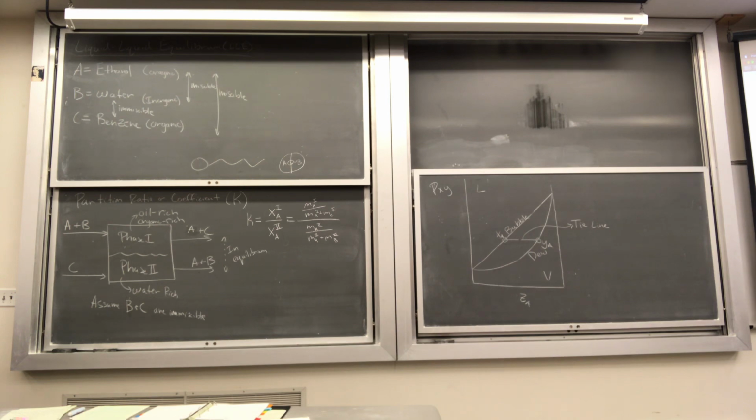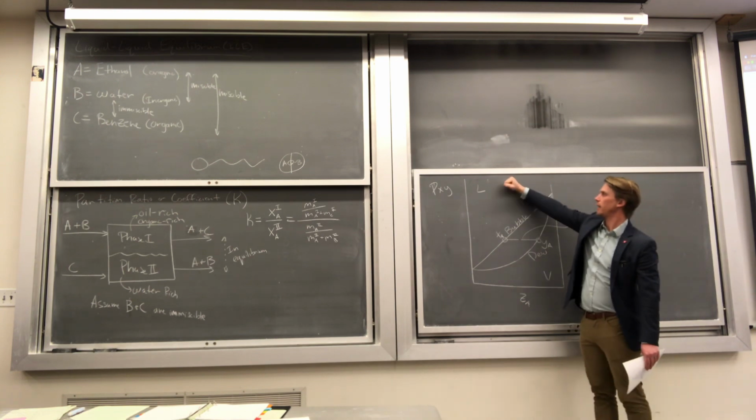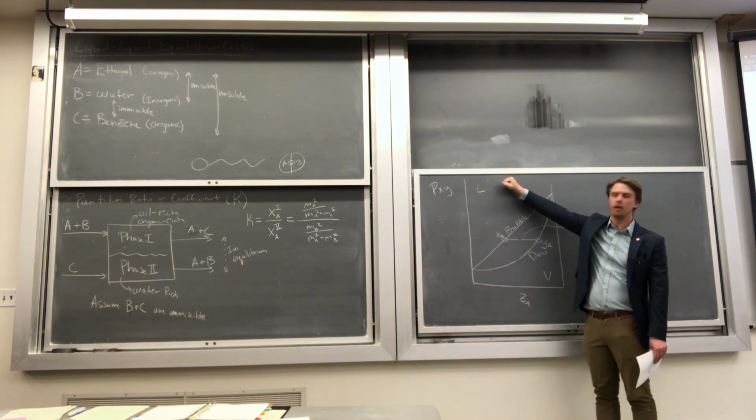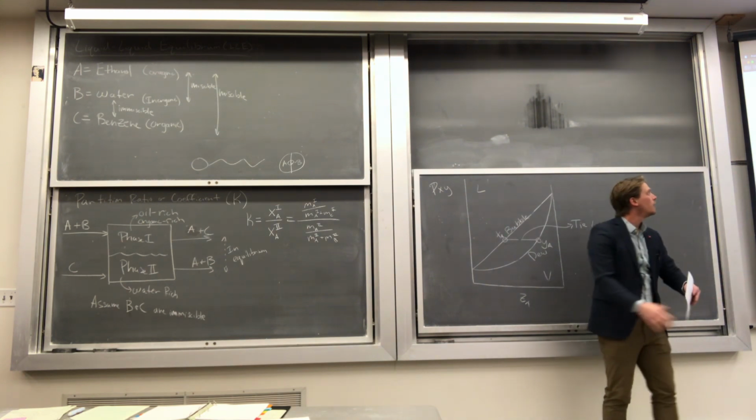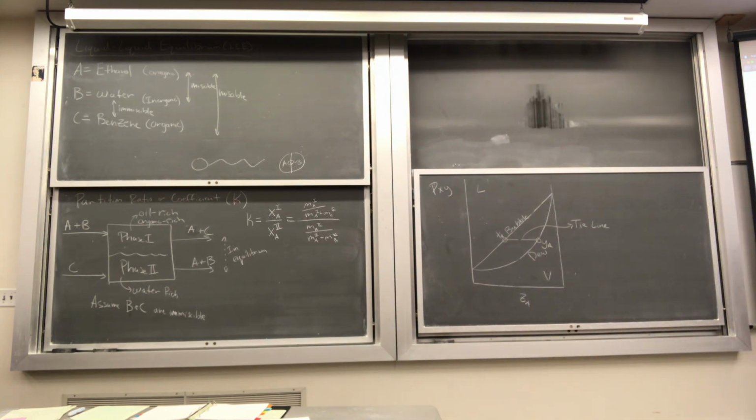Now, let's do point 3. What is the total composition of the system at point 3? And then as a follow-up, what is the composition of the two phases that form? So point 1 is an example on the PXY diagram as being up here, 100% liquid, or down here, 100% vapor. One phase, infinitely miscible, right? There are no multiple phases that form up here.